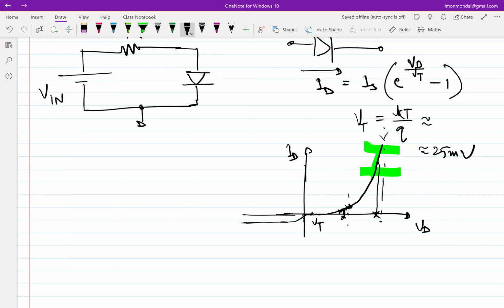So generally, what we tend to see is that if you use silicon diodes in the range of milliamps of current, let's say a milliamp to 10 milliamp, then you get to see a range of voltage, and that range of voltage is quite similar to 650 millivolt or 700. I don't remember whether it's for germanium or silicon. Well, let's say for silicon, let's say it's 700. So in the range of milliamps of current, the observed voltage is of the order of 700 millivolts.